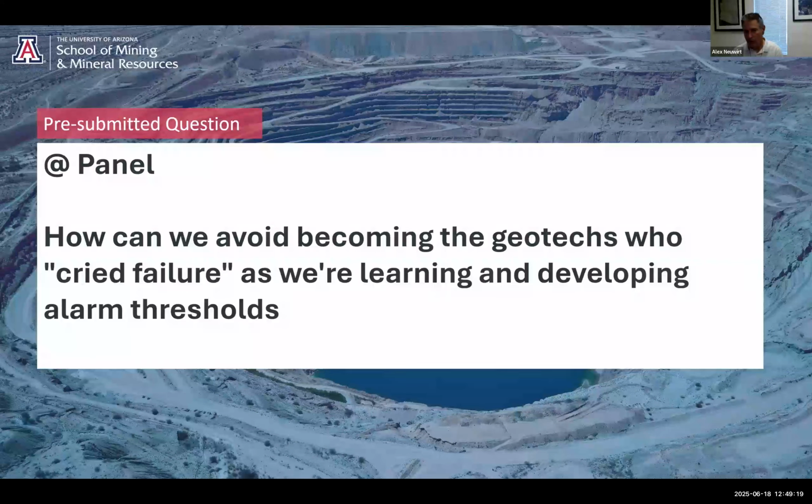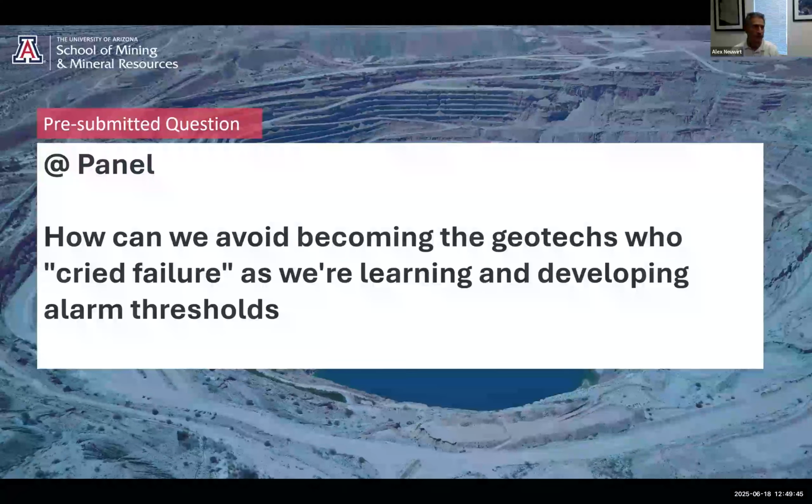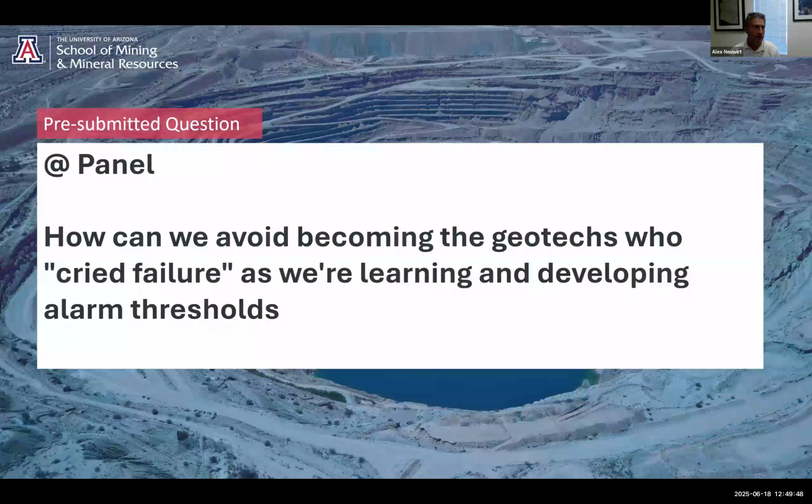So, to your reluctance, Paolo, you said something to the effect of you're a little afraid of these alarm thresholds, and maybe that's where you're coming from? I've observed this too. If alarm thresholds are not part of a process of learning and developing, it's a disaster. I've been to mine sites where I'm literally looking at the screen that they're using for monitoring their radar, and it's flashing red every 8 seconds. Well, that's not an effective risk management system. That's just a screen that somebody has to pay attention to every 8 seconds.